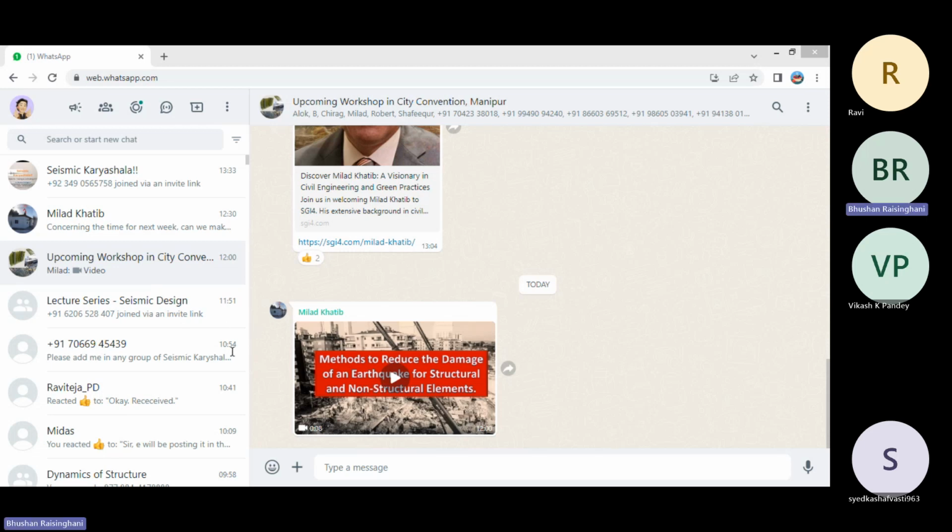Requirement is the same as for the column. In the boundary element, 0.8% steel minimum, 0.8 to 6%, and 4% to avoid congestion, in the boundary element should be provided as vertical reinforcement.